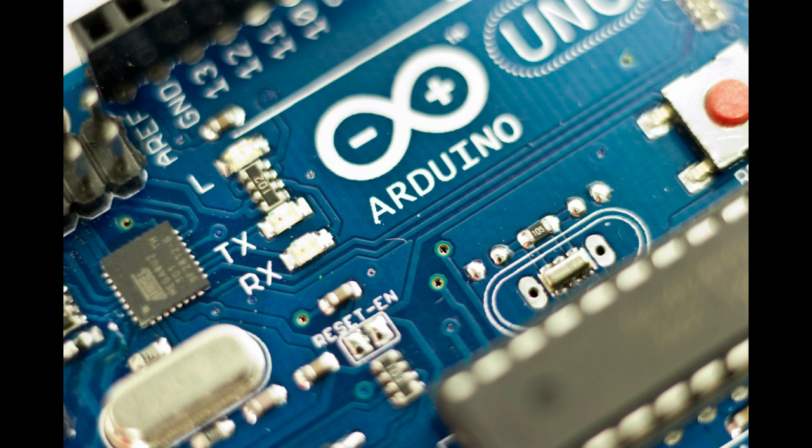The board has 14 digital input and output pins, 6 analog input and output pins, and is programmable with the Arduino IDE. It can be powered by the USB cable or by an external 9-volt battery, though it accepts voltages between 7 and 20 volts. It is similar to the Arduino Nano and Leonardo.